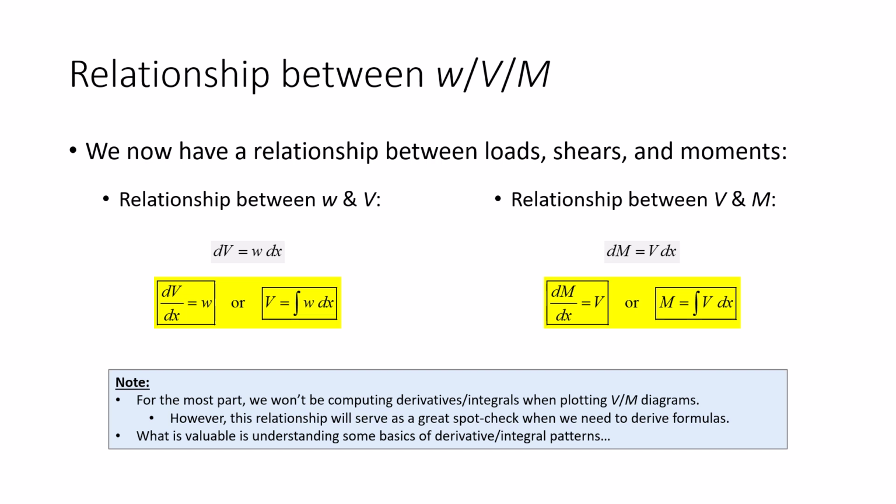to shear to moment. So in order to construct our shear diagram, we need to integrate the loads. And in order to construct the moment diagram, we need to integrate the shear diagram. Now, I'm sure as I'm saying this, you're thinking, oh God, Calc 2 all over again. Oh no. The benefit of the types of problems that we're dealing with is as follows.